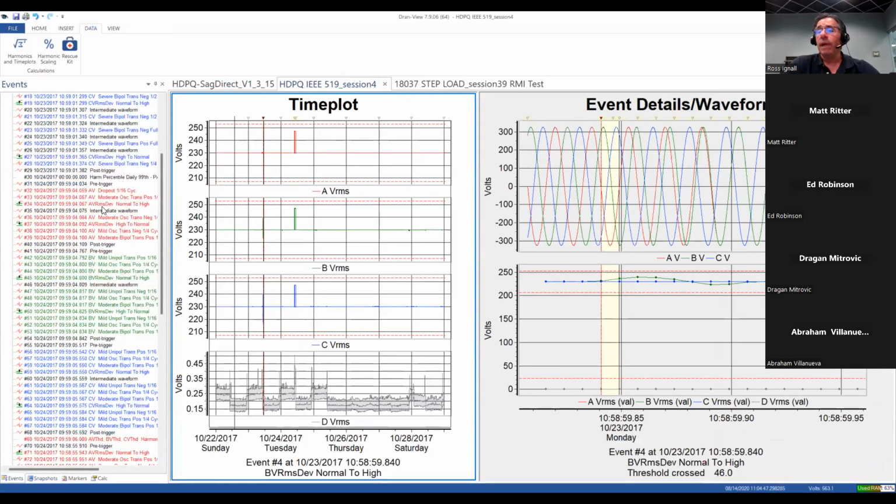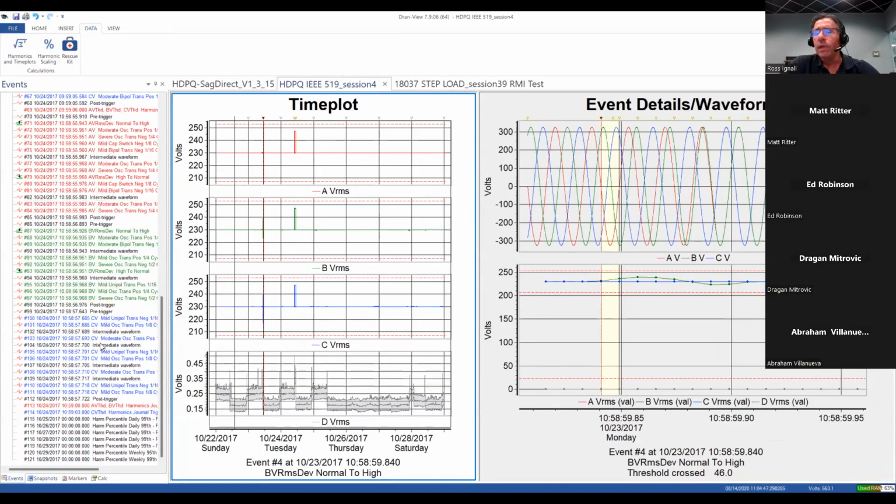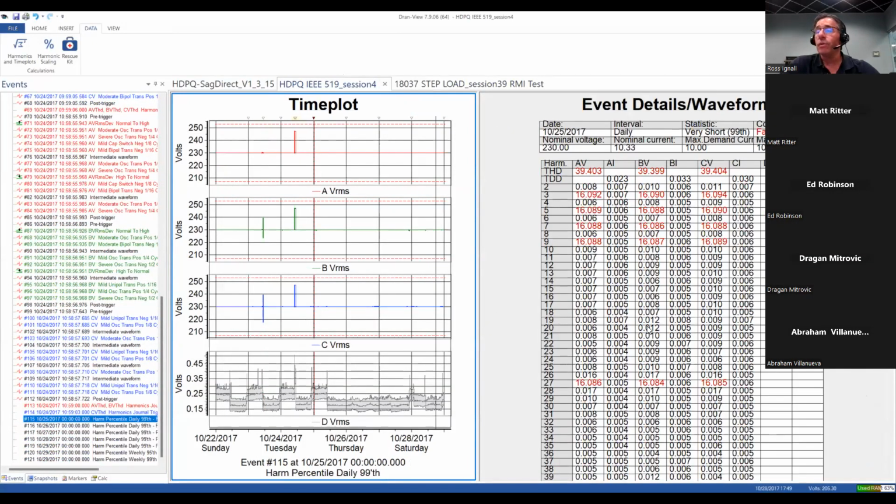So we'll look here, and if I scroll down, you will see my individual compliance reports based upon this standard. You will see the pass/fail. This happens to be a test that we did in our lab. This is not a real customer for this particular report, but you can see the THD failed, and these are the individual harmonics in red that were out of the limits. These limits are defined by IEEE 519 2014 in this particular case for both voltage and current. It's based upon the nominal voltage and the short circuit current, the available current in the circuit, that is used for that.